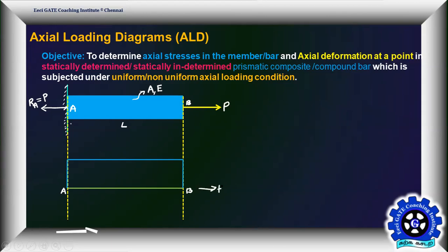This is P actually. This is of course positive. So in this direction you assume it to be positive. Now I'm here seeing the load. Both are acting in the same direction. You need to move up. Don't lift your pen until the next load comes. Now I am here. I have seen the load. Both are acting in opposite direction, which is negative. Negative means you need to move down by P. Throughout the bar, it is subjected to P and it is positive.